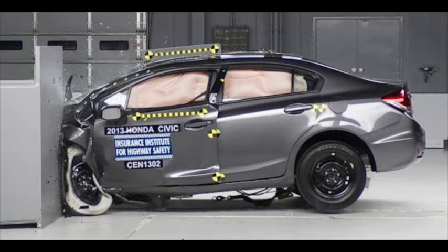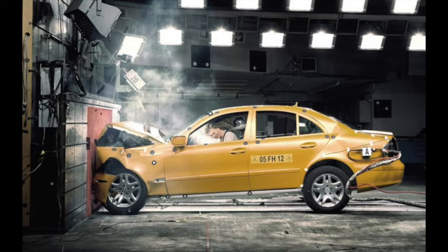Based on our resources and time constraints, the car safety feature we settled on adopting was the crumple zone design. The whole purpose of it is that during a collision, it increases the time over which a change in velocity or momentum will occur. This will significantly reduce the impact that the car driver and passengers face.